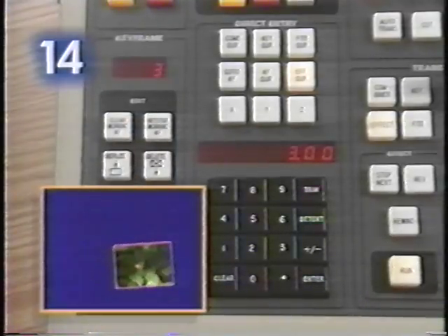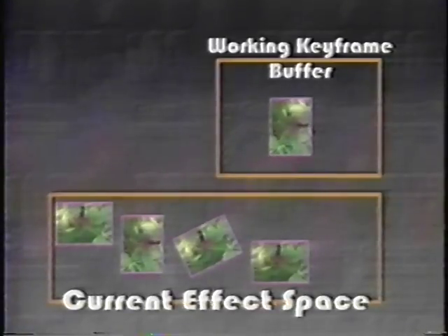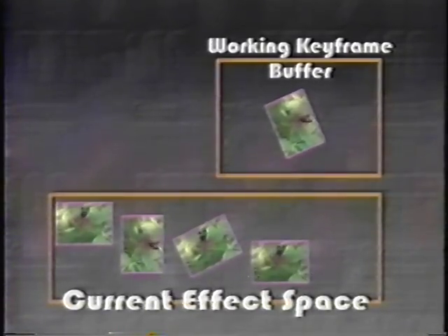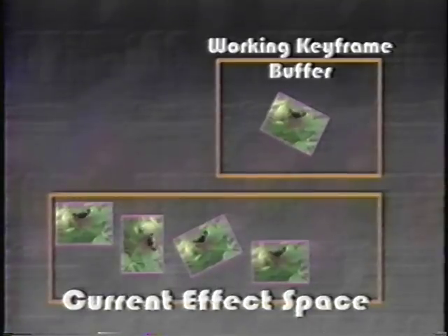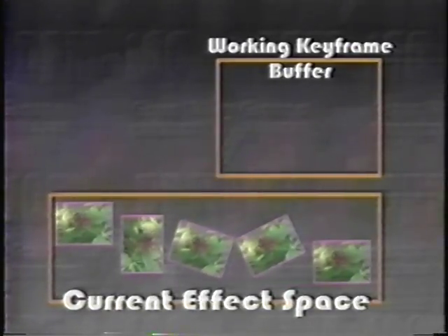You can also insert a new keyframe at a point between two existing keyframes instead of before or after. The new keyframe will be inserted into the path between the two frames and will split the duration time which was originally between the two.